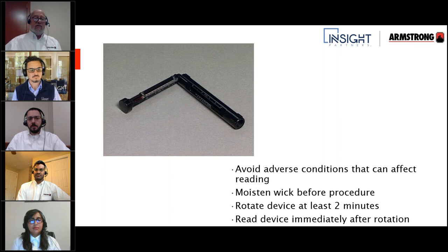The key to it is not getting in places with high wind. So you kind of have to be in somewhat of a sheltered area if you're trying to read outdoor wet bulb and outdoor dry bulb. And you don't want to wait a long time after you've taken your readings. But it's really simple to use. And the cool part is it doesn't require batteries.